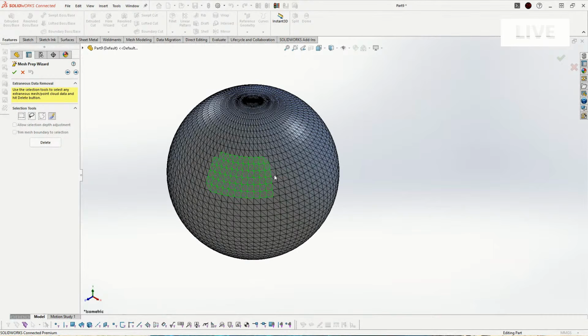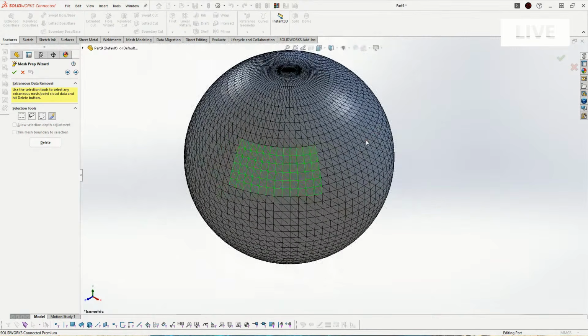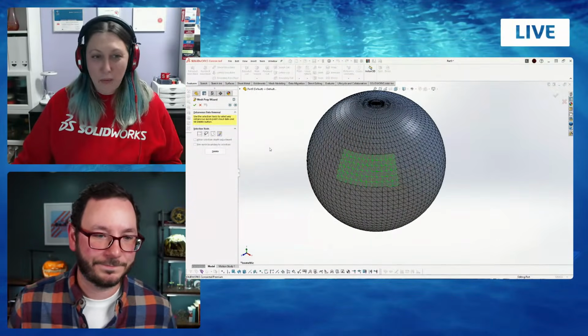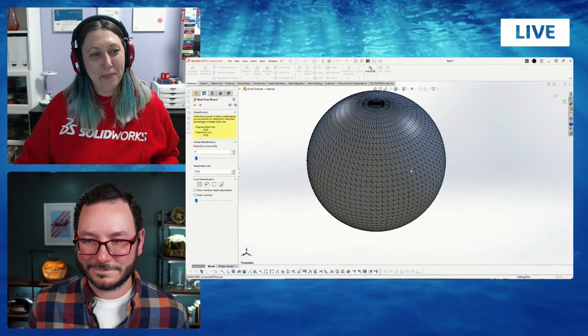An interesting thing that I found out, because of course we know with Control you add more. But what happens if you by mistake choose some triangles you didn't mean to? Then you go with Alt and click, and remove them. Nice, great tip. So I won't delete anything. We will just go to the next step.